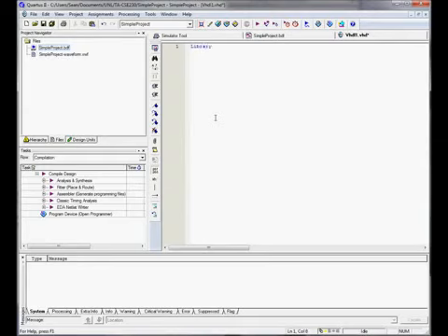The big one is IEEE. This has standard definitions for things like logic vectors for buses and sometimes some math functions as well that you might want to use. And we need to use this library, so we're going to say use IEEE standard logic 1164, which defines a bunch of different variable types, all, because we want everything.